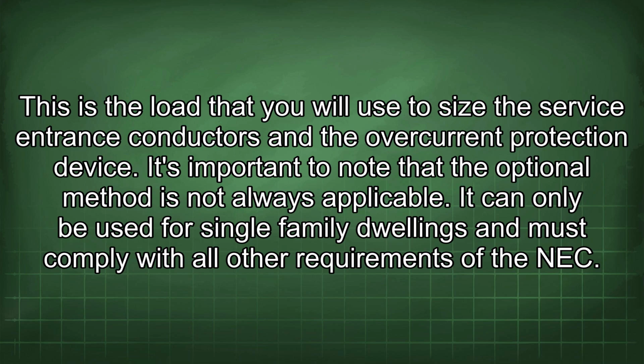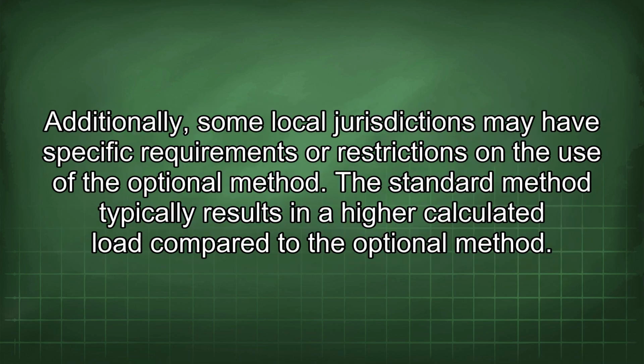It's important to note that the optional method is not always applicable. It can only be used for single-family dwellings and must comply with all other requirements of the NEC. Additionally, some local jurisdictions may have specific requirements or restrictions on the use of the optional method.